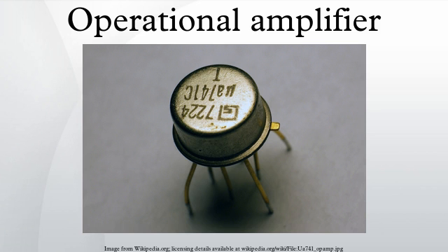Because of the wide slew range and lack of positive feedback, the response of all the open-loop level detectors described above will be relatively slow. External overall positive feedback may be applied, but this markedly affects the accuracy of the zero-crossing detection point. Using a general-purpose op-amp, for example, the frequency of VIN for the sine-to-square wave converter should probably be below 100 Hz. Negative feedback applications, non-inverting amplifier.